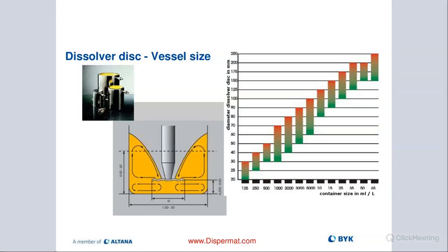But before we go there, we would just want to recapture a few important points for the pre-dispersion process. So it's really critical that we select the correct diameter dispersion plate relative to our container size. And you probably know that there is various sizes of dispersion plates, and there is not one that's always correct for the one type of container.